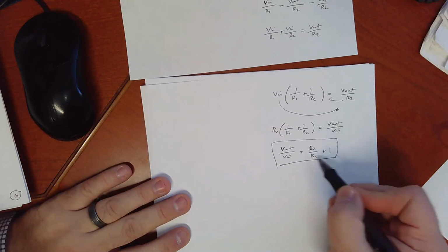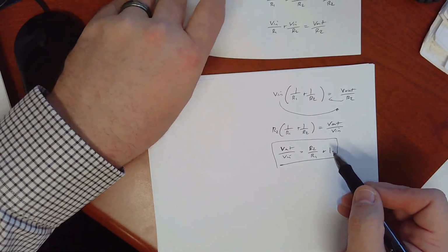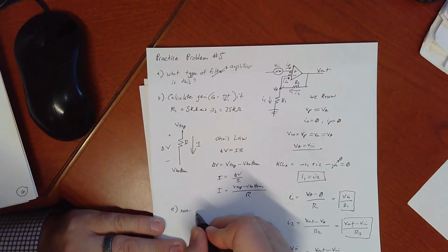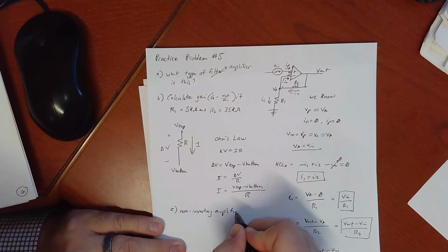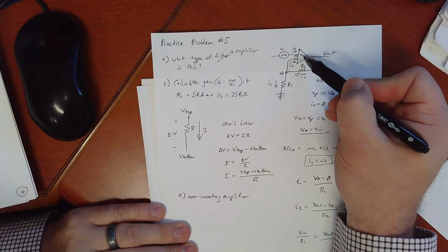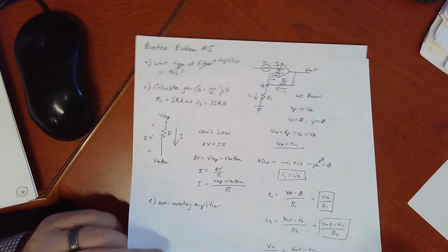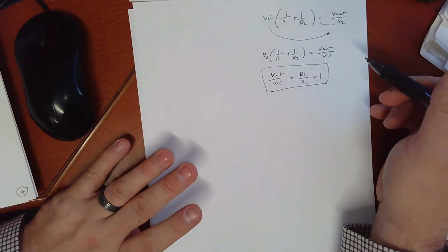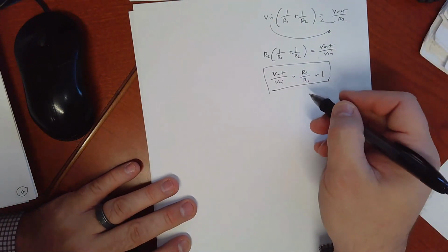And what we see then is that the gain here is positive. And so what type of amplifier is this? This is a non-inverting amplifier. One way to look at that is the input's connecting to the non-inverting positive input, so that's kind of a giveaway of what it is. Now, if you knew this by inspection, and you knew the gain equation, well, then you could substitute right in. So now we can calculate the gain for that.